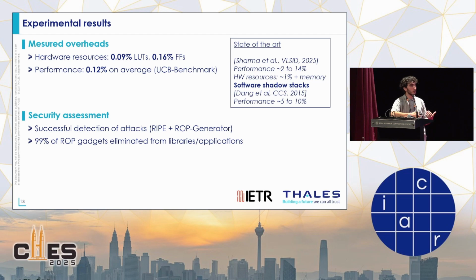In comparison to software shadow stack, this is very interesting in terms of performance, and compared to hardware-assisted implementation of shadow stack, it's also interesting because we have less performance overhead and less hardware overhead and no memory footprint that would be the result of storing the shadow stacks in the memory.